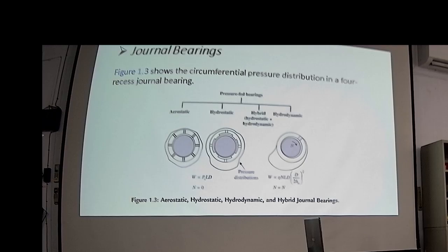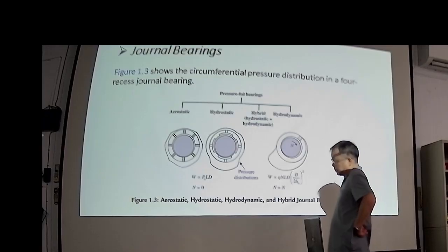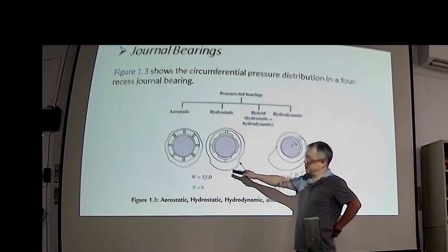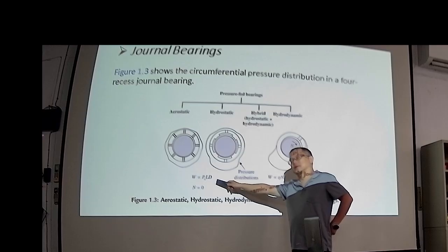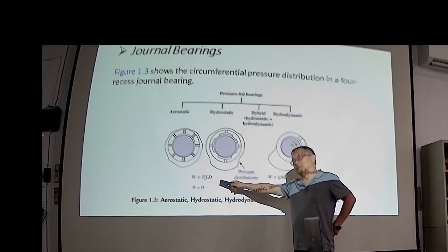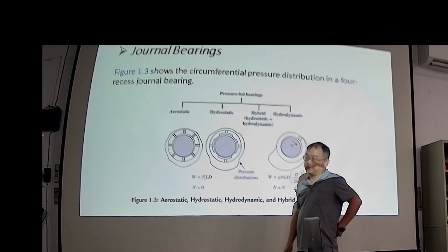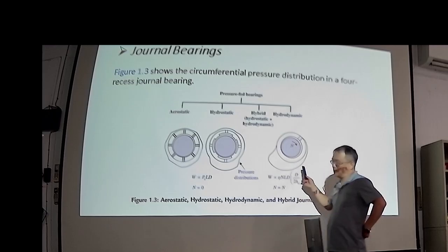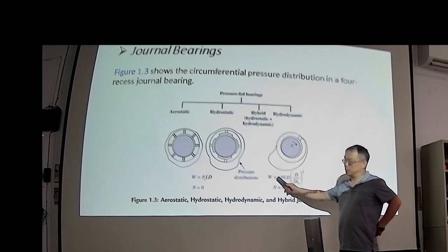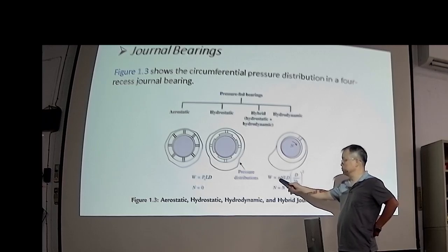But the difference is that the load capacity for the hydrostatic bearing is not dependent on the rotational speed. But for the hydrodynamic bearing, the load capacity will be dependent on the rotational speed.